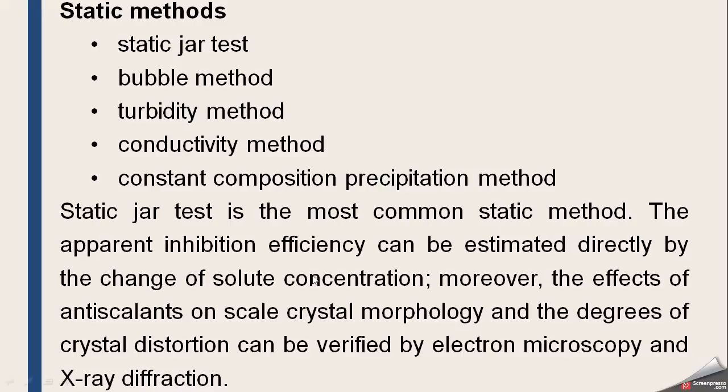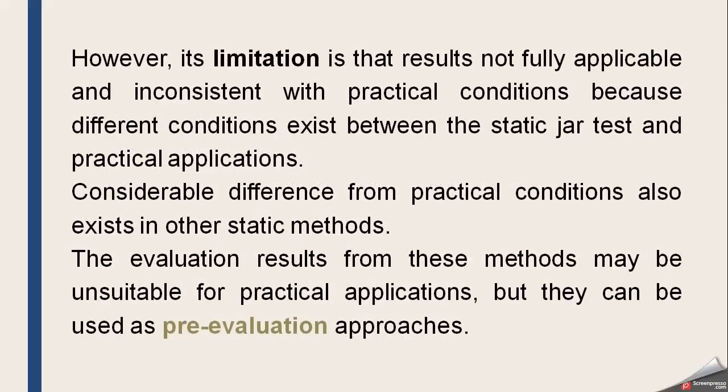The effect of antiscalant on scale crystal morphology and the degrees of crystal distortion can be verified by using electron microscope and X-ray diffraction. When we add the antiscalant to the solution in the jar, it will react with those impurities, and whether it will settle them or keep them in suspended form in the water can be checked with the help of other techniques like electron microscopy.